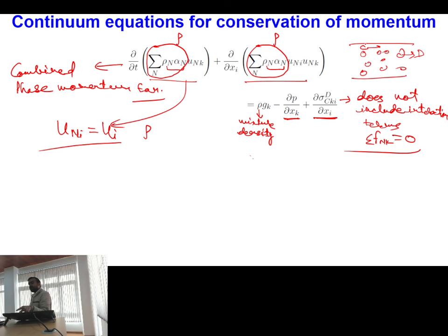I have to simply determine the mixture density, and using that mixture density I can solve my momentum equation. So in the stress tensor, the shear stresses will then become zero? No, shear stresses will only come because of the continuous phase, because that is our assumption. Why are shear stresses zero?